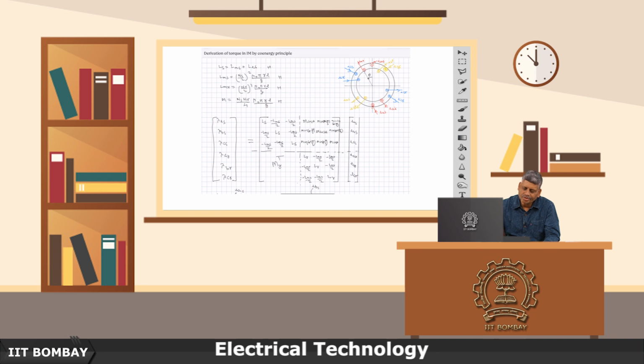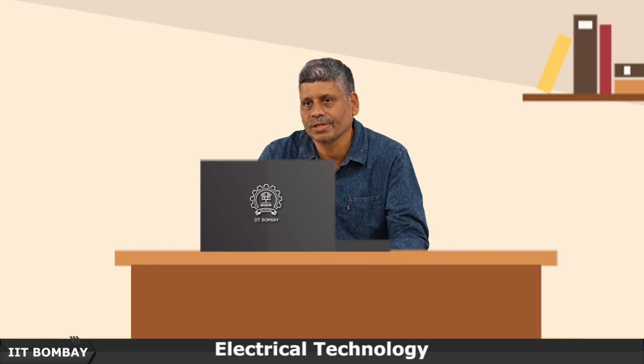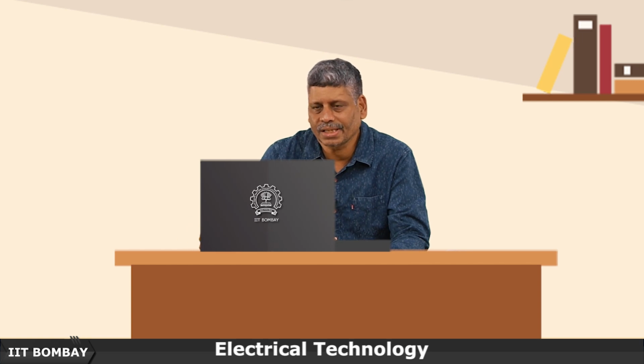Basically, derivation of the torque from the principles of energy or co-energy is a fundamental concept which is very closely related to the physics of the problem, and I have been trying to follow that line right from relays, actuators, synchronous machine. Of course, it is not used in transformers because it is not a rotating machine. When we are talking of torque as a function of the rate of change of angle, the synchronous machine, and then automatically the natural consequence is that it should also be done for the induction machine.